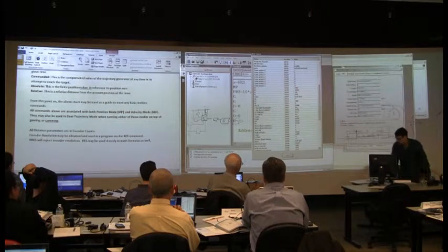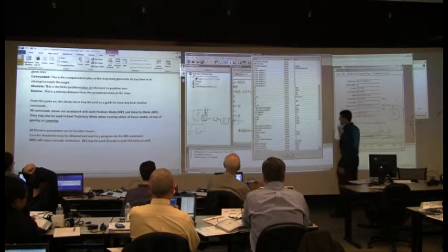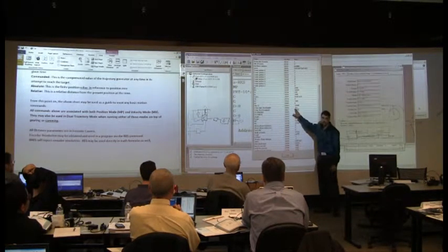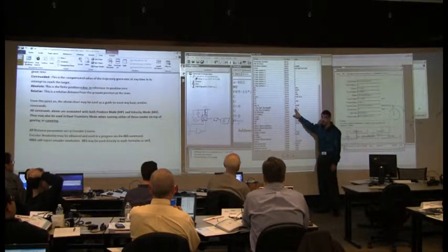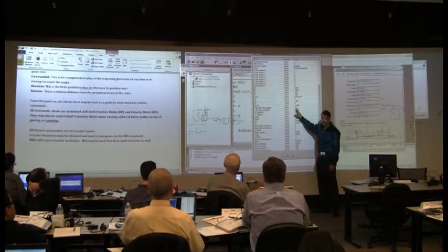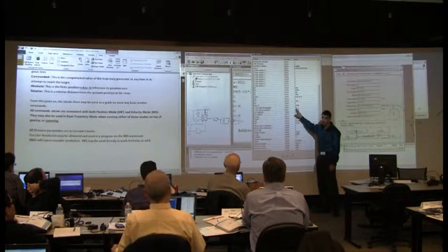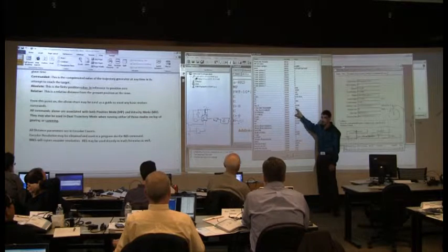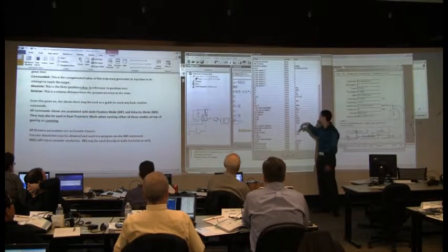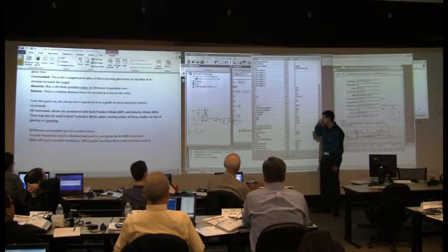Heads up to the Ys. We had the wrong value in here last year for a while. So there are some motors out there that if you get unknown trips and don't know why, and your customer's getting ticked off, give us a call. That may be the reason. The value was accidentally put in at 13 for a while, which would have been 52 volts. That was way too low. We didn't find out until later, and then of course we fixed it. So just be aware that that was the case.